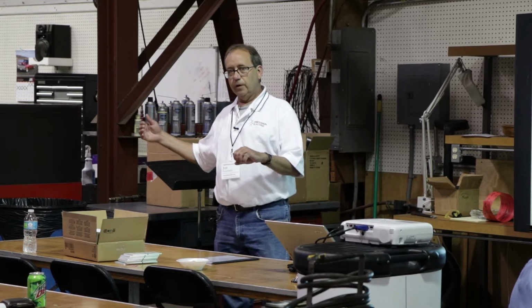the conductor. So in that same relationship, the higher the voltage with the same size conductor, you're going to have more current flow, right? You want to get more volume or less friction in the pipe, you make the pipe larger. So friction makes heat in conductors, and the more current you have flowing, the more friction you have, the larger the conductor you need to keep it all within a reasonable temperature.